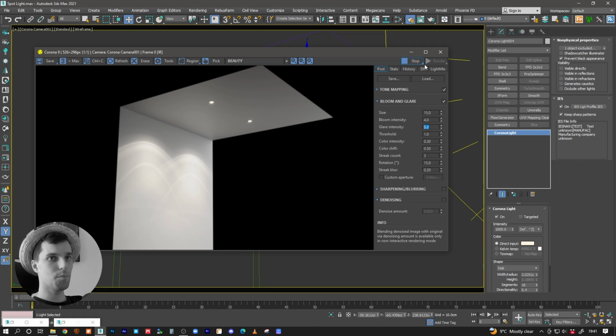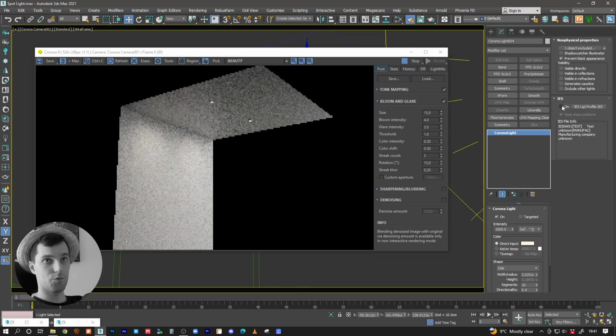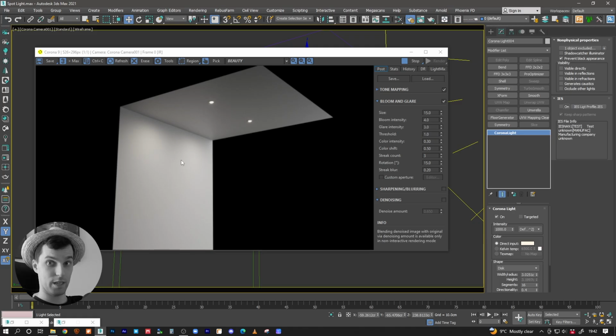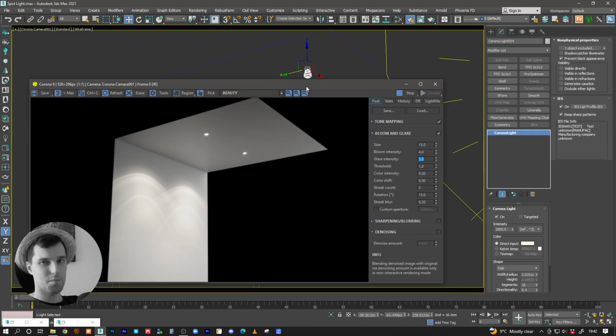But in general, I'm just going to remove this. And as you can see with these soft lights, it's a lot harder to spot where exactly the light source is shining. But sometimes you have IES lights that are very wide, and it can cast light from very far away. So for example, if you move the spot with the IES profile somewhere there, it can still cast the profile on the wall even from 1.5 meters. Perfectly, it can perfectly do that. It depends on the IES profile. But I hope this makes sense.